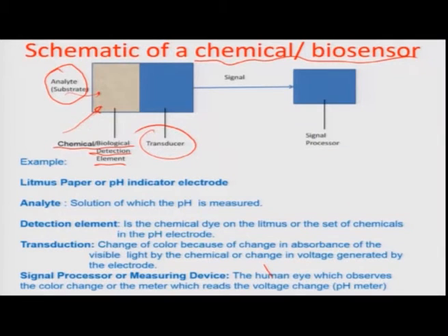So, for such a change in response, let us say we are talking about a gas sensor. If there is an element which takes up a certain gas from a set of gases within the environment and changes some property, say it starts releasing electrons, thereby making positive ions and changing the conductivity because of the release of electrons due to the reducing gas that comes in, then it can detect a reducing gas by change of resistivity.